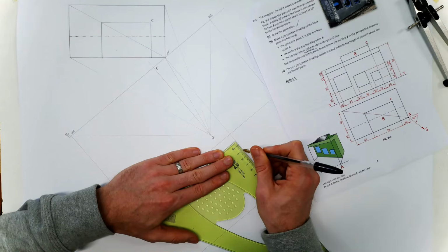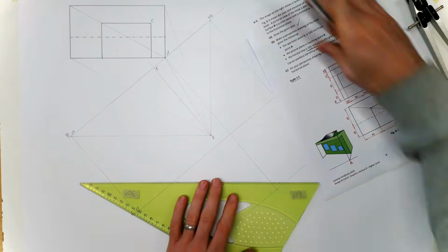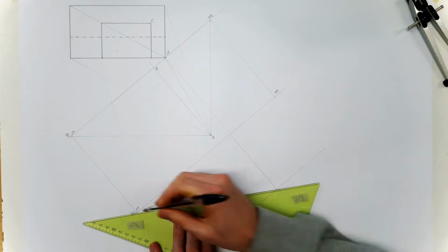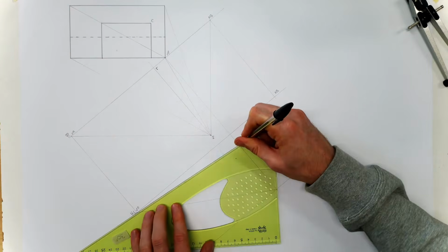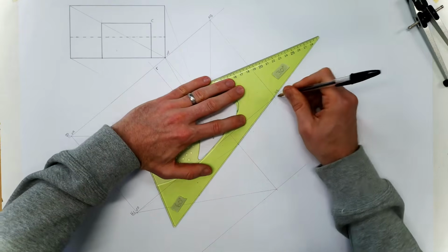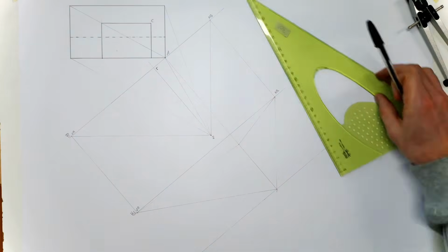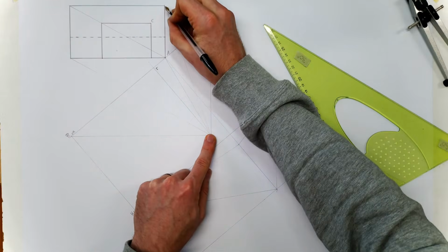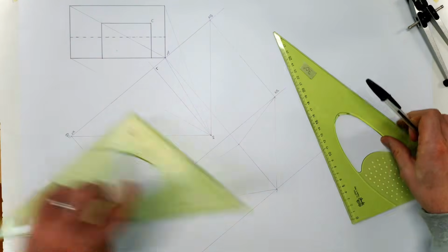So let's measure 85 and down 10. And I'll start vanishing stuff now just to get the overall outline of my object. So we've got vanish, vanish, back to my VP1 and VP2. And here, that's my viewing point from the spectator. That's where that edge or that side intersects the picture plane. Same on that side. So let's bring them down.